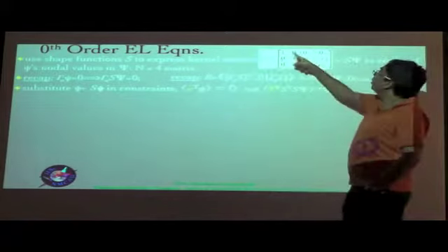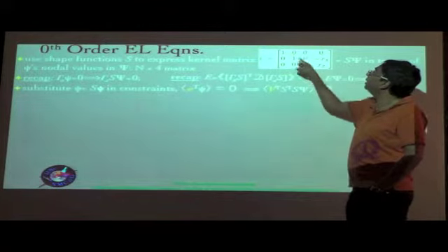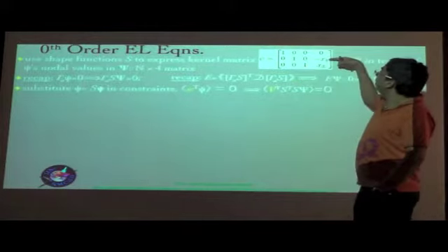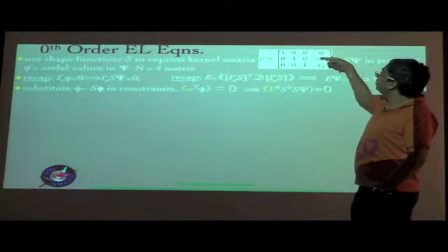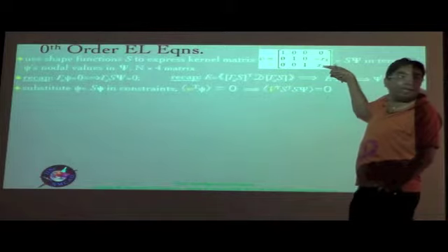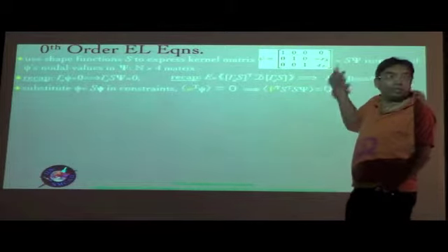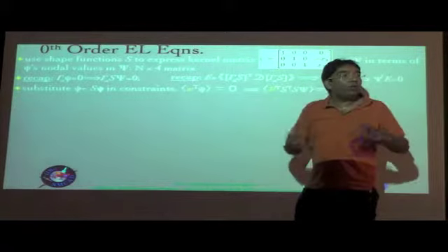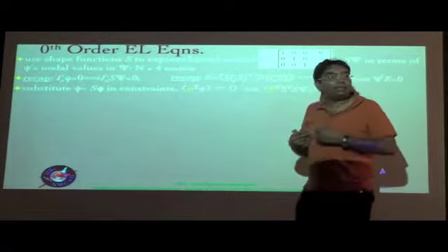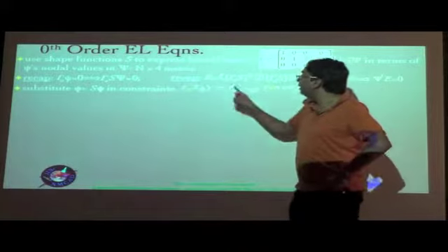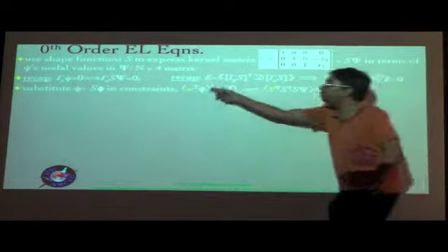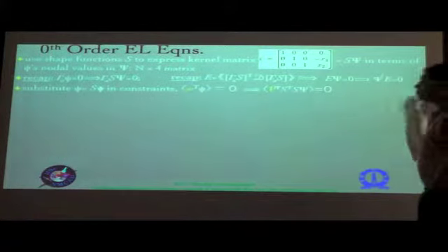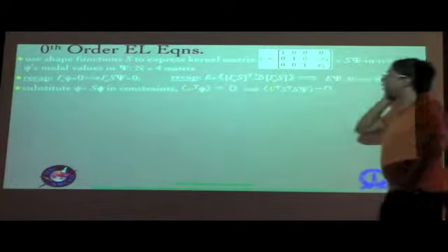It's quite easy to see what it means from these three: average of W1, average of W2, and average of W3 equal to 0. And here, W2 times x3 with a negative sign, added to W3 times x2, integrated over the cross section equals 0. So that is a compact way of putting all the four rigid body constraints into a single thing. In fact, it is from this that we derive those scalar representations of the constraint. It is a matrix equation representing the set.